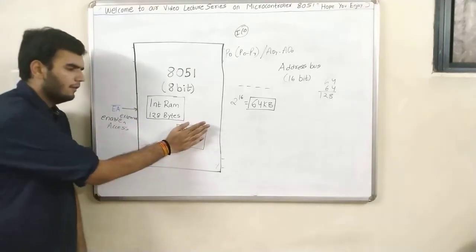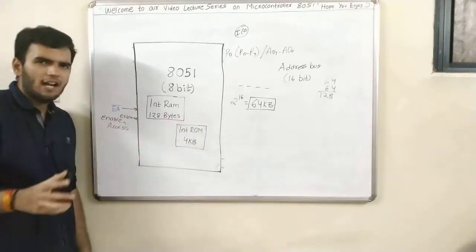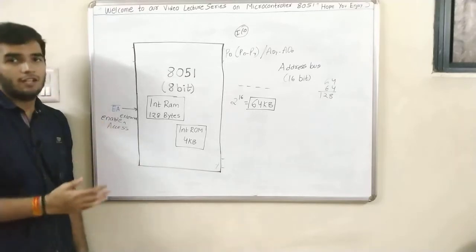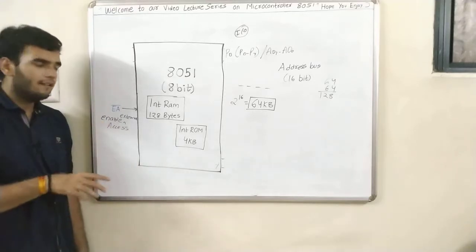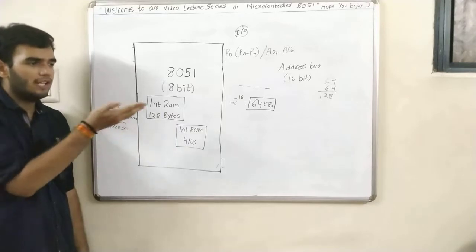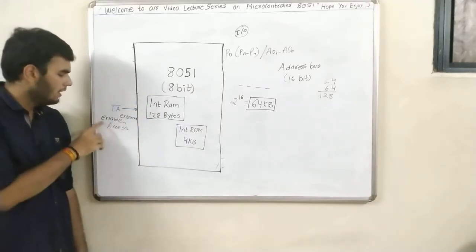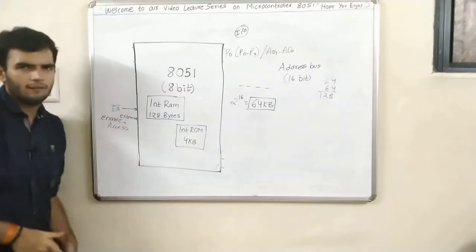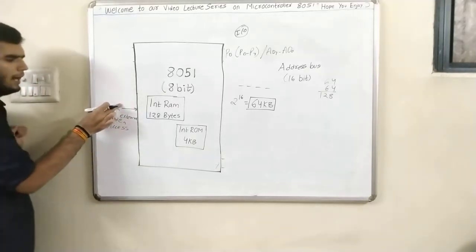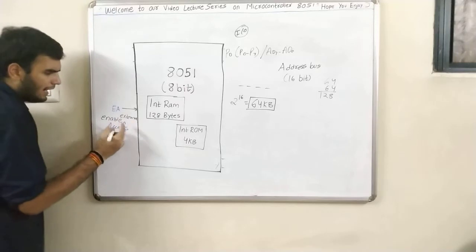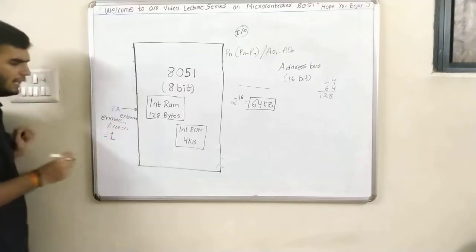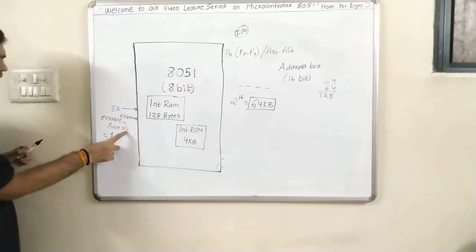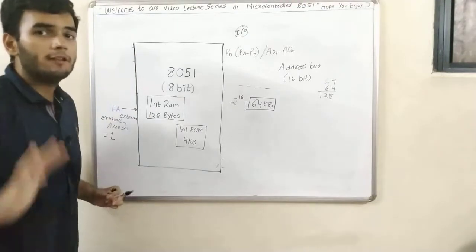You will basically electrically discard it and connect the external ROM. So in this situation, to know whether we are using an internal ROM or external ROM, this is used. So what it says, enable external access. If this bar was not given, and this is 1, we can see that there is an external access and external ROM is used.